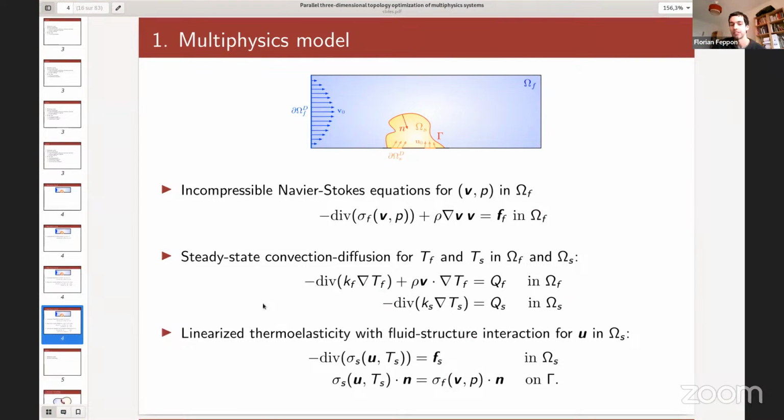Right now I have not worked yet on the two-way coupling, but it's much more challenging because the coupling from the solid to the fluid would involve nonlinearities with the deformation of the fluid. You have to transport the fluid variable in the deformed configuration, or the solid variable in the deformed configuration, and this imposes nonlinearities which can be difficult to treat.